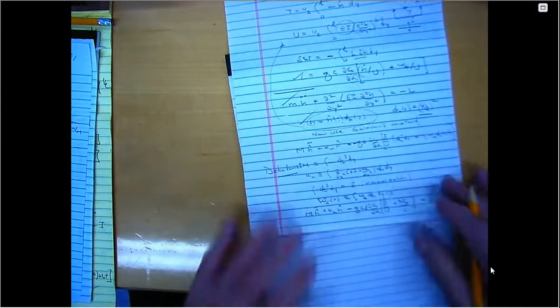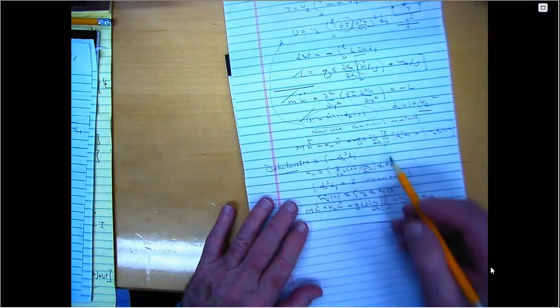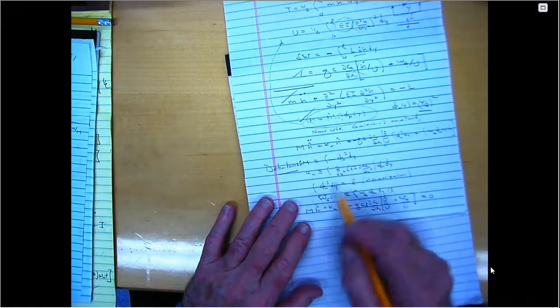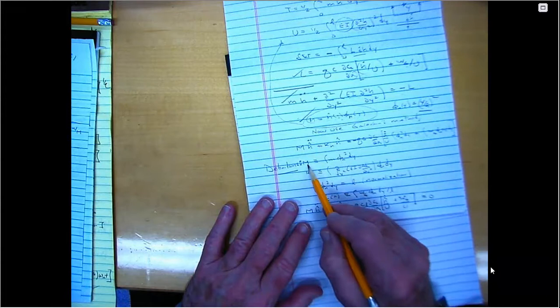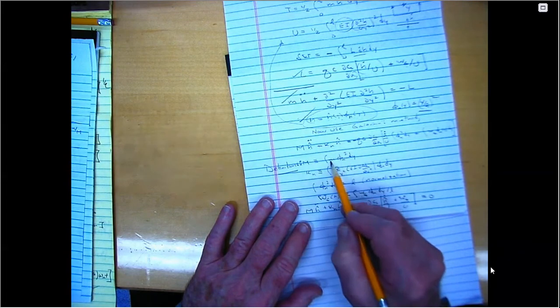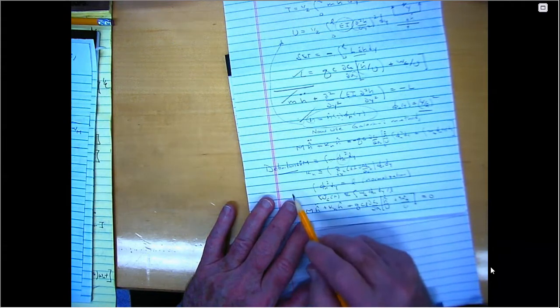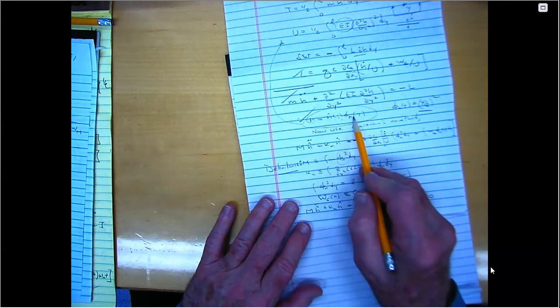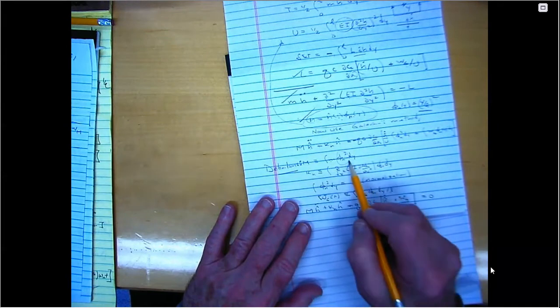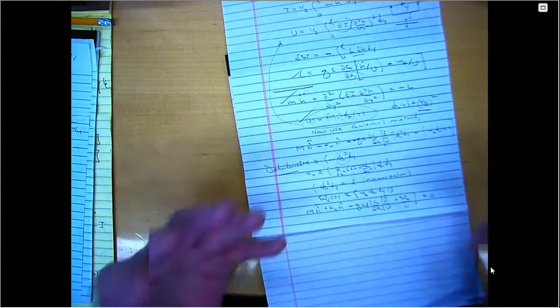Okay, so now some definitions. There's some coefficients here, and they involve these integrals. This physically is the total mass weighted by the mode shape, right? This is the mass per unit span, integrated over the span. So this would be the total mass of the wing, except there's a weighting factor because of these mode shapes that we use. So this is called the generalized mass. It's not the physical mass, but it's a mass associated with the mass distribution and the mode shape.